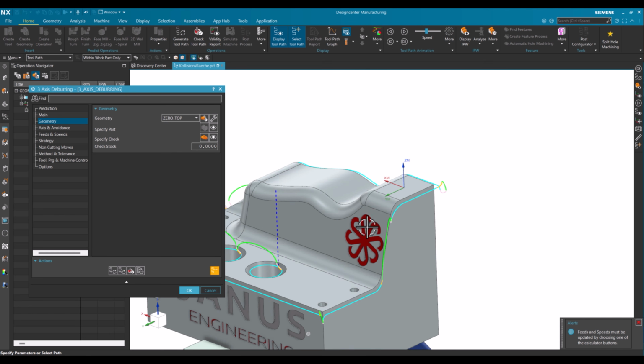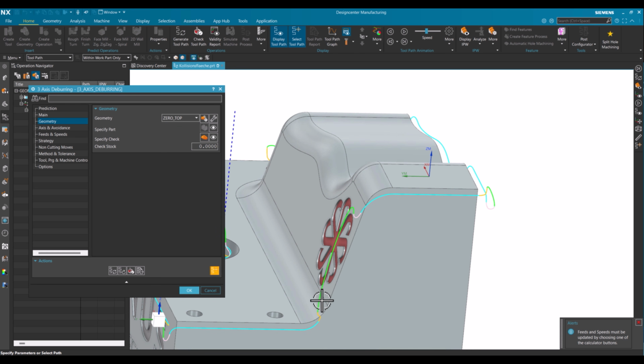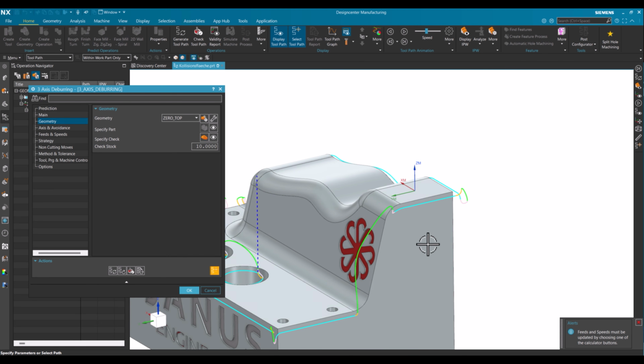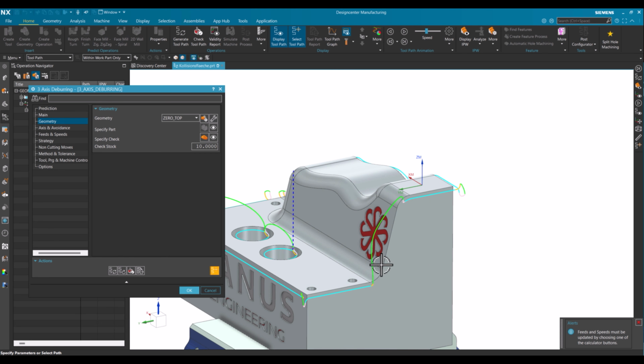And we can see it's now moving away from the surface here, and it's approaching the surface once more further down below. What we can do now, for example, is to slightly steer this path here using a collision measurement. Just to mention here, also in the upper area, please ensure to avoid scratching this surface at all costs. I'll have it generated once more. This way, we can precisely control where the tool should move and operate.